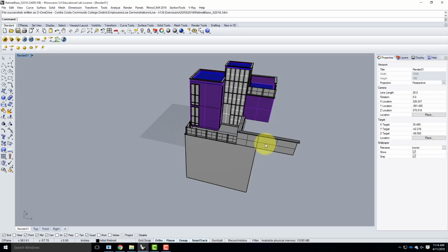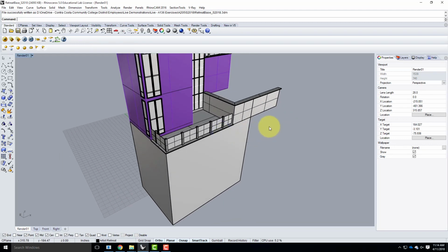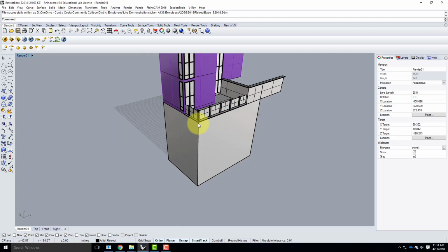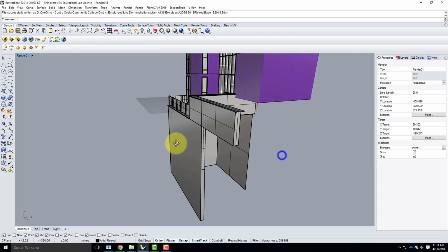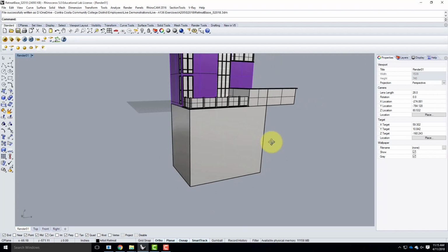There's a few pieces that, as you're looking at it, look a little funny. This wall here, for example, is a retaining wall. It looks a little funny with no site there, but I'm guessing, because I haven't actually put this into the site, that the site's going to come down along here and I'm going to need this wall. Furthermore, I know that this building's going to be sticking up out of the ground because it's on the side of the hillside, so I've given myself a bunch of extra wall down at the bottom. It's much more than I need, but it's going to intersect with the site and help that happen.